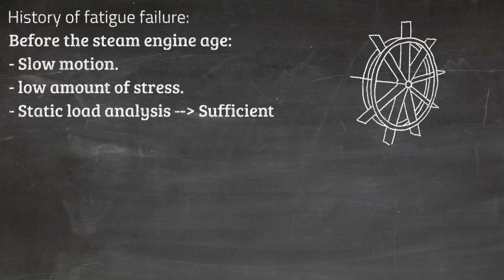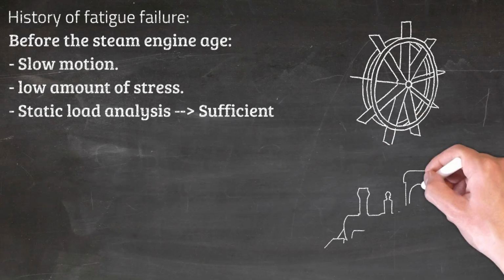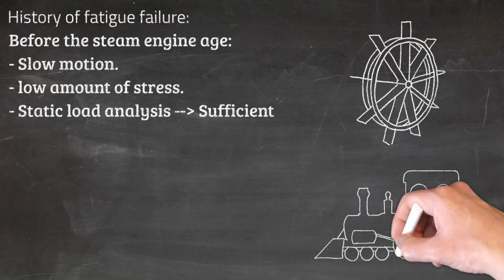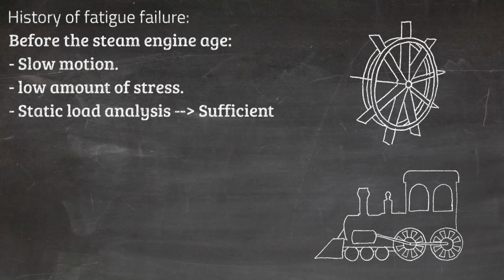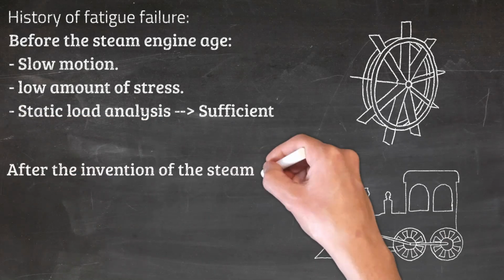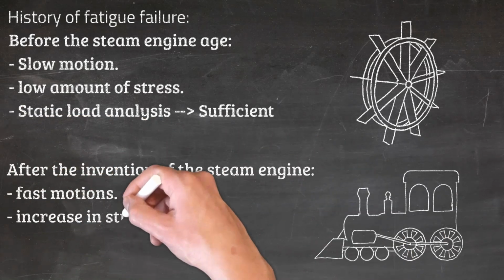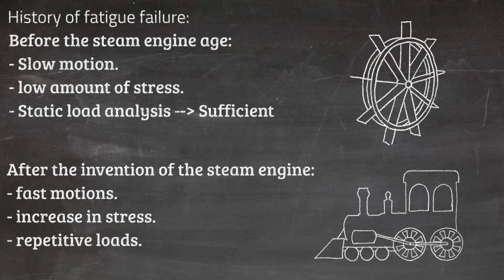With the emergence of steam engine-powered machinery and faster motions, things changed. The mechanical systems used were under larger, repetitive loads. Varying or repetitive stress is an important part of fatigue and its analysis. There would be cases in which the stress value would completely reverse from tension to compression in a mechanical component.